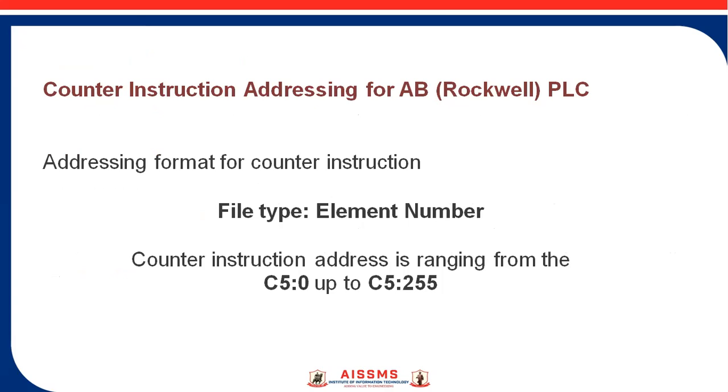Let us see addressing format for counter instruction for Allen Bradley PLC. It is file type colon element number. Counter instruction address is ranging from 0 to 255.